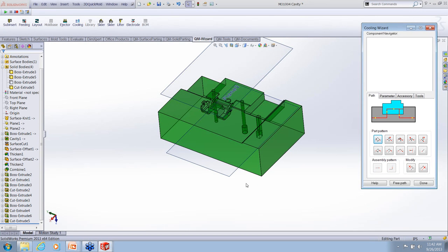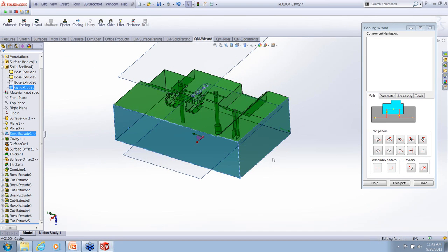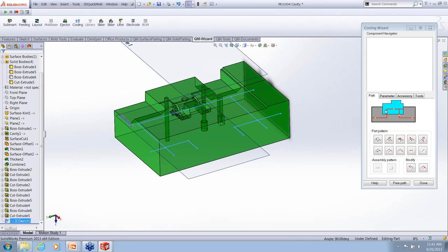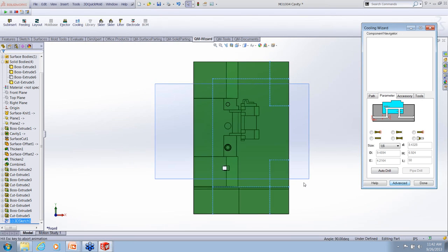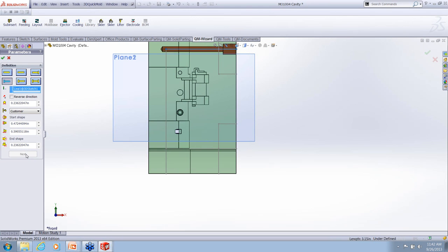As I told you earlier, for cooling channels, predefined sketches are already there, but we can use predefined sketches, or else we can even directly create some sketches to define cooling channels. There are already sketches there, so I just use that to create. Direct parameters are there to add cooling channels, and different types of holes are available here. Let's have a look at this one. The moment I click this one, the same shape will be available here. So I'm just going to add this one here, and then I'm going to select all the lines, cooling channels.